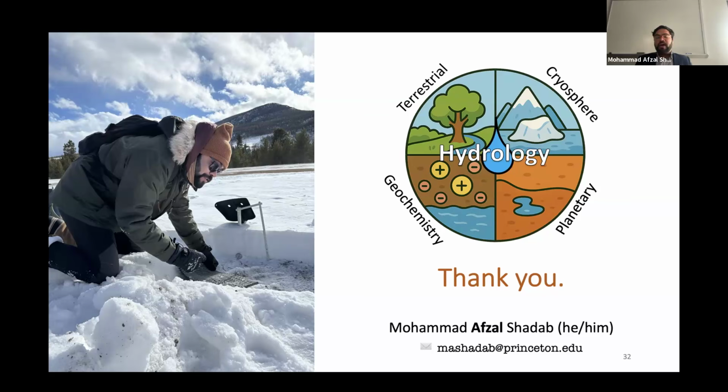That's a great question. Right now, I have not considered the ice sheet in it, but the model can have an outflow. Currently, we are working on connecting this with impermeable ice layers. So there is no motion of ice in this model, and that is something for the future work. For the boundary conditions, it's just outflow at the bottom, so liquid can actually go out of the domain. What other models do is assume once it's out, that is also called runoff, which is not exactly the case. It can do a lot of things if it is out of the domain.